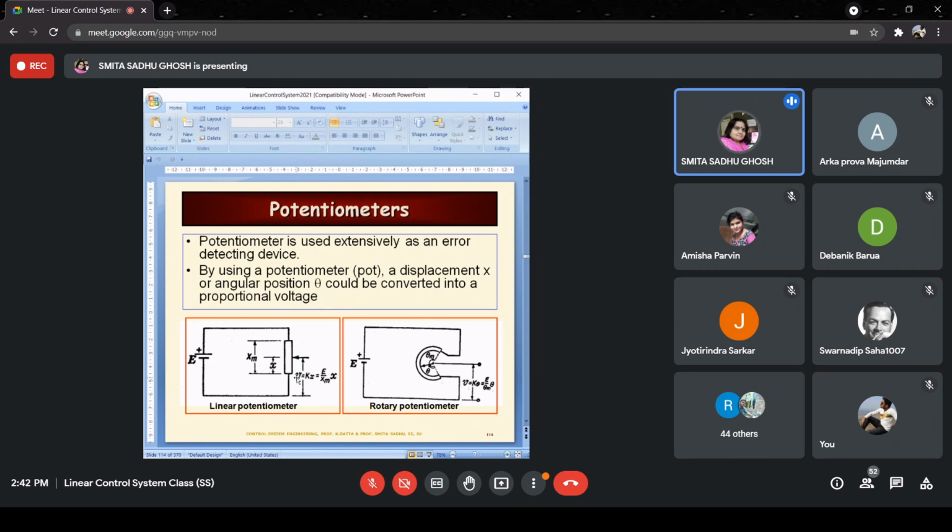So now the voltage at the output side will be proportional to this length, because this length will be proportional to the resistance, right? If the overall resistance of this element is proportional to Xm, this portion of the resistance is going to be proportional to this x, right? So V, the small v, that is the voltage at the output side, is proportional to the length of the element over here, namely small x. So V is equal to some constant times small x, right?